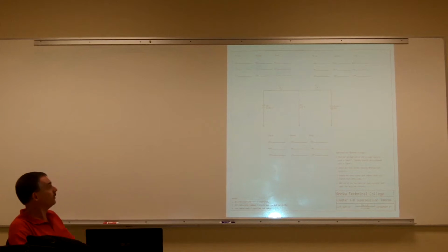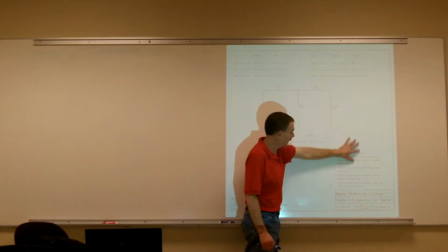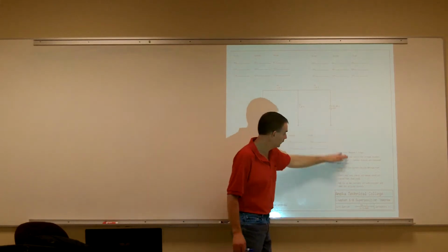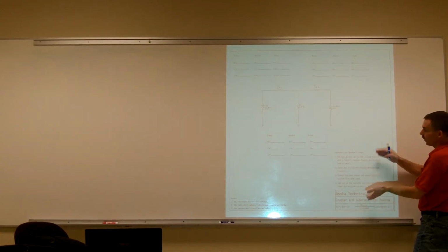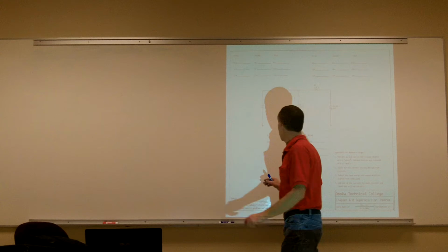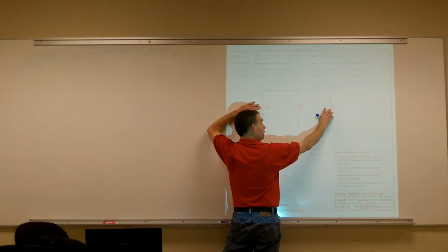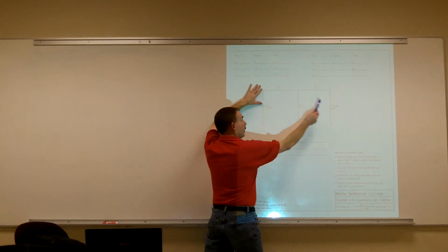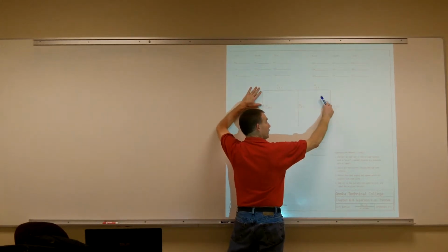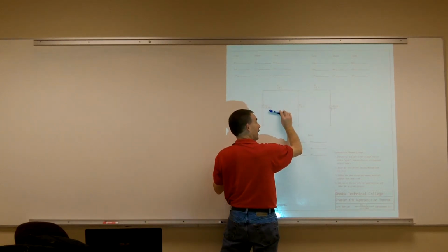All right, so again, if we just follow the procedures, we can solve for all these answers. Now here's the procedure. But what's really going on is what we really need to know. When we're working with superposition, it means that we have 2 sources going in there. Well, when we're looking at these sources, this source doesn't even realize that this source is in there. It's just a direct short for it. And so that circuit looks different than what this source is going to see.